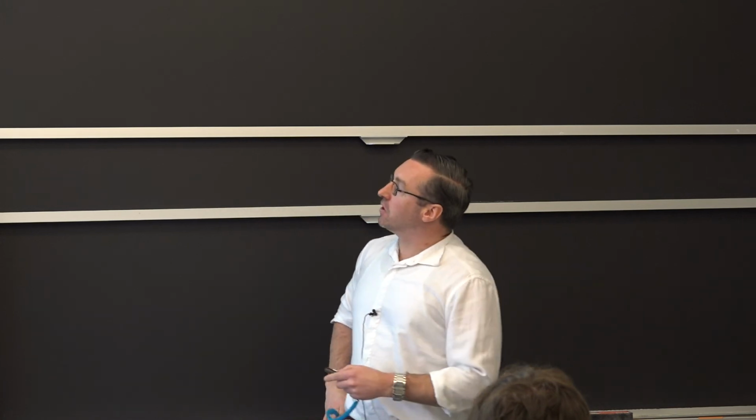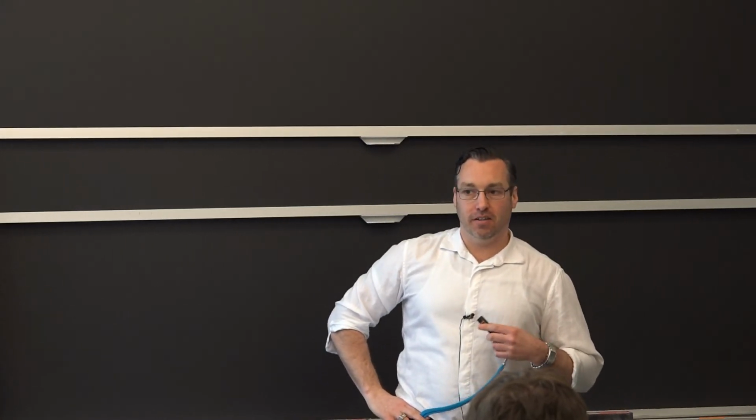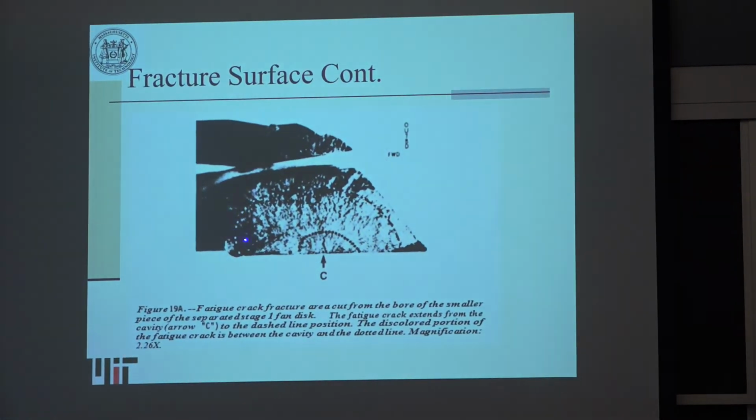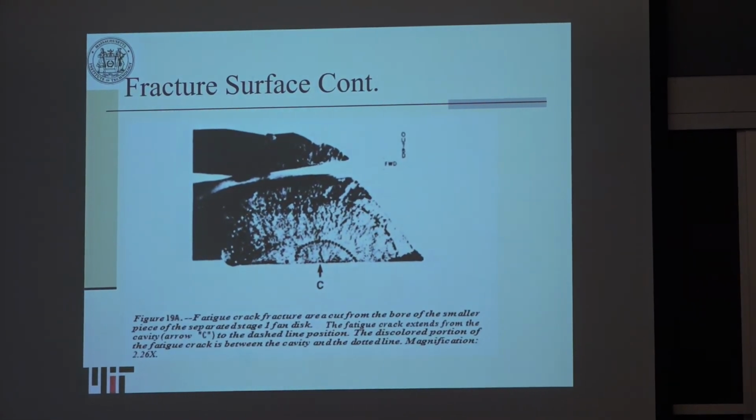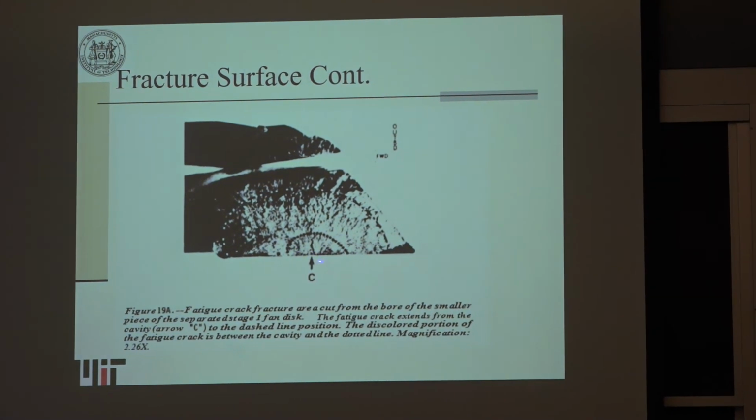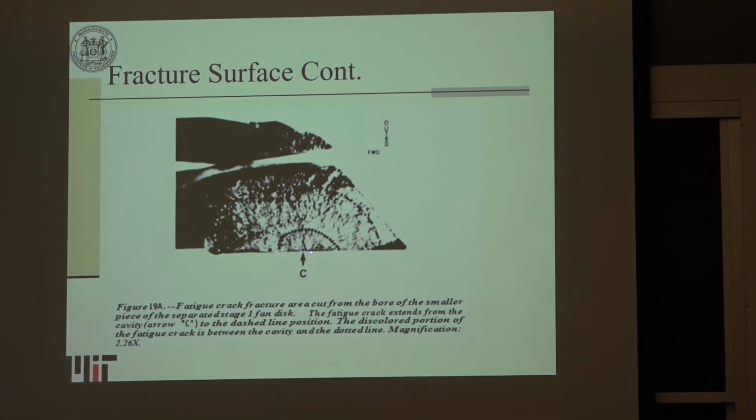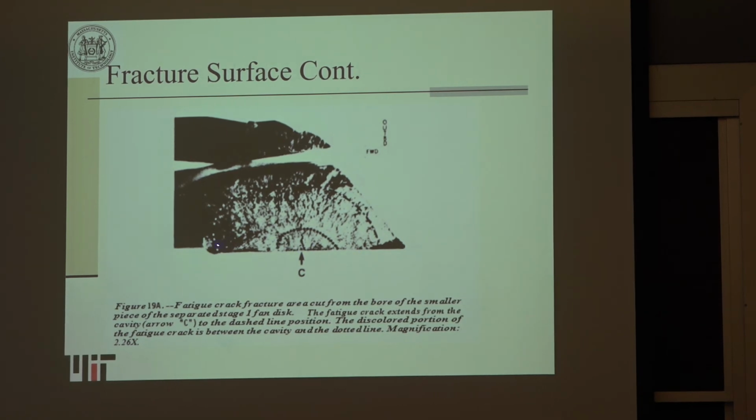So this is your fracture surface. This is how you know it didn't happen upon impact with the ground. When you do a root cause evaluation, you'll get the fracture surface. When they're talking multiple origin locations, you would look at this cross section here, and you'll see the ratchet marks here. They progress in what's called beach mark formation. So it actually goes in a thumbnail fashion.